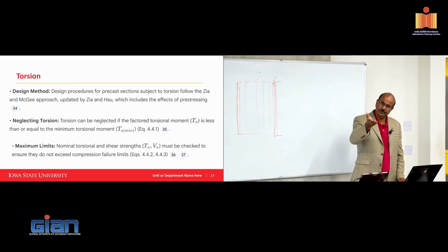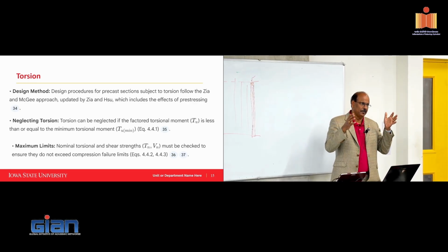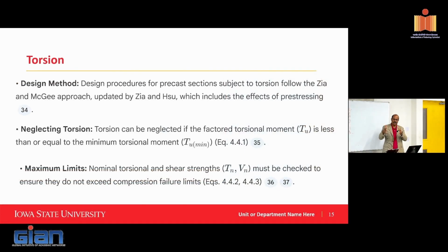Again, Satya touched on the torsional issue. Torsional issues come in because you are supporting beams or floor slabs on one side of the inverted T, which induces the load temporarily. Even if it's temporarily induced, if you create torsional cracks, the stiffness of that member goes down significantly. So you want to prevent that from happening.